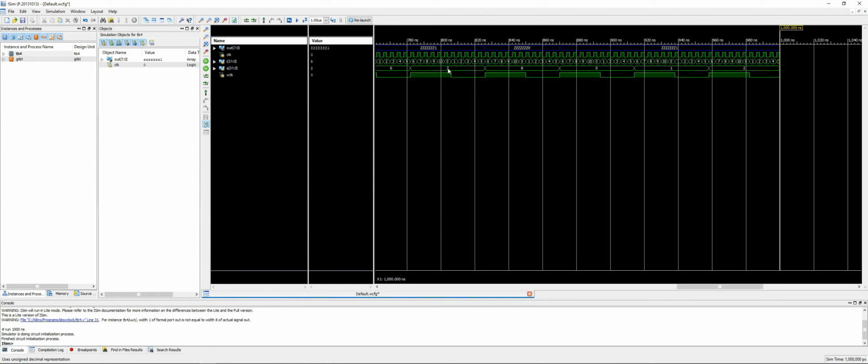You have to observe the timing diagram. Once you find any problem here, then you're going to rectify it. Same goes here, 0 until 10, right? Because you want 0 until 9, so that it becomes a 5, right? Because 0 until 9 we have 10 different states, right? So change it. When you observe the timing diagram, you know where you can do the correction in your coding. This is how you learn.